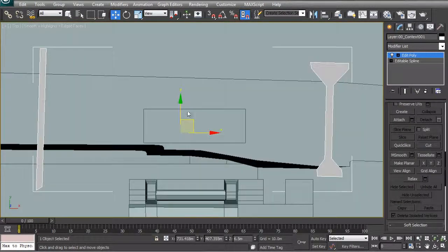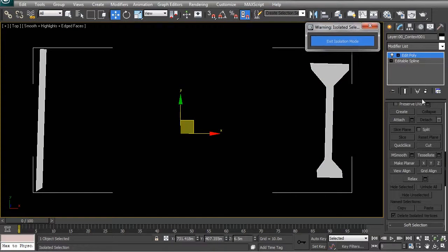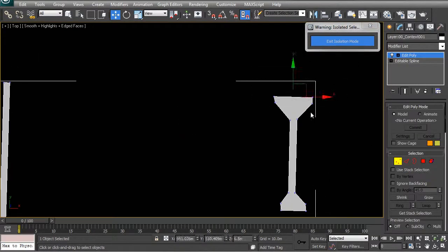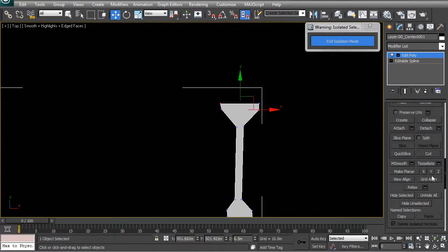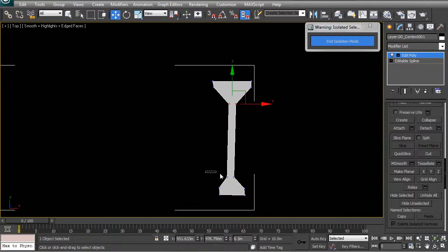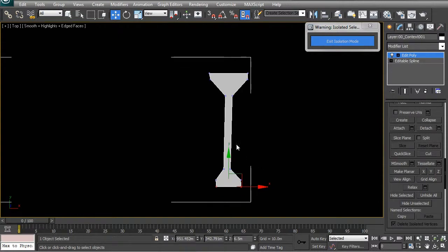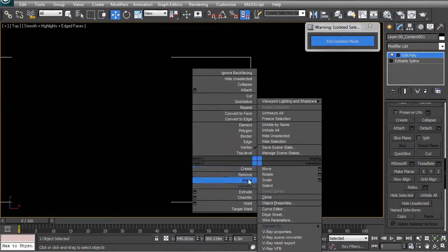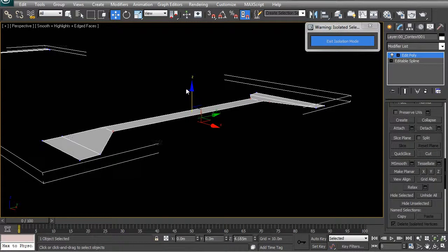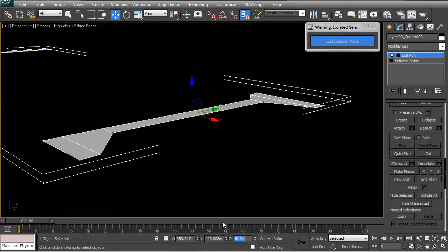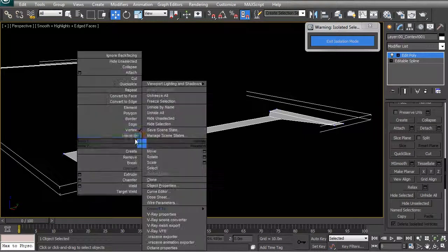So in the case of the bridges, let's just isolate those, and let's first of all neaten them up slightly so we can make them planar in the Y direction. And I'm just going to work on one to quickly show you the way that I would very simply and quickly create a low poly bridge that we can use in our site model. Now I would take these 2 vertices, each pair at a time, and right click and connect them, and the last pair here, and you can then take your central area, move it up slightly. Let's say you're going to move it to 10 meters, and then the rest of the bridge stays as is.